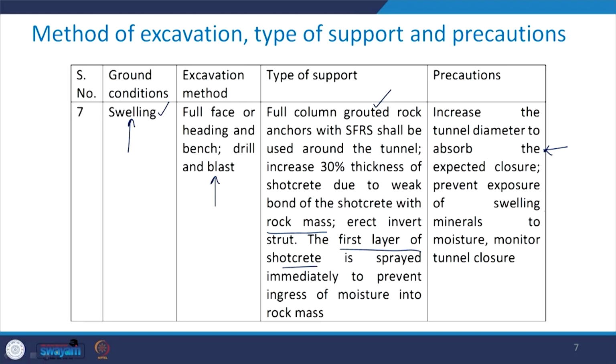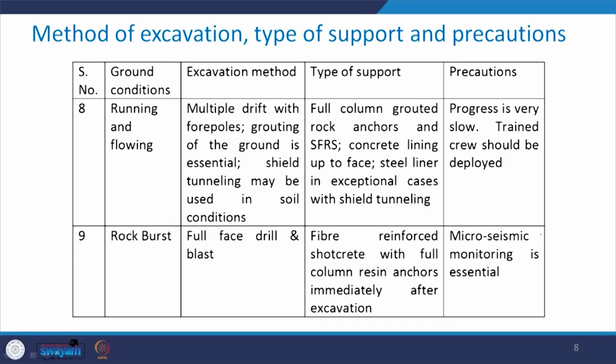Prevent exposure of the swelling mineral to moisture, and we need to monitor the tunnel closure. That means instrumentation is required in this case as well. Next, the ground condition includes running and flowing, and the excavation method recommended is multiple drift with poles.